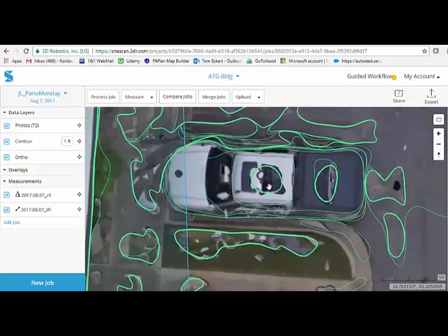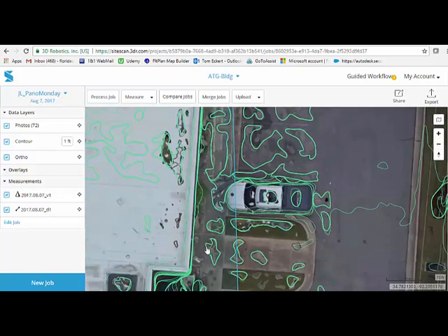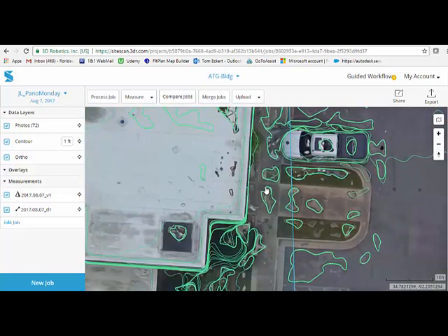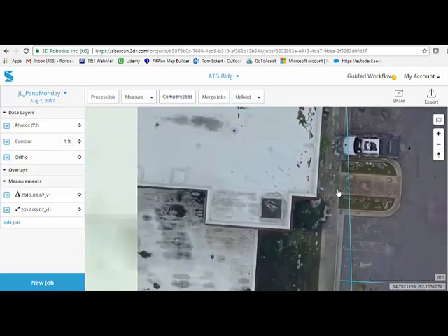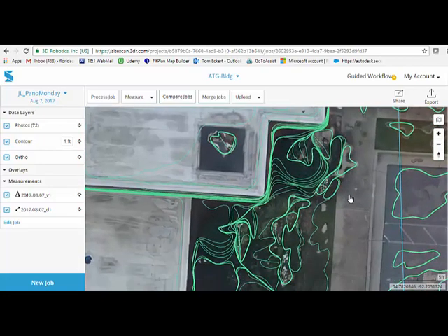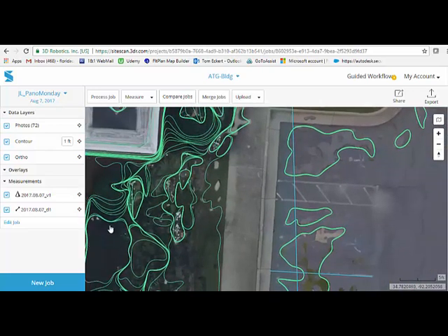So don't be fooled when you contour a vehicle as a surface object or use these contours for development without fully understanding the metadata, the point groups, and the precisions and accuracies from a full geomatics perspective. So yes, it's a feature, and we don't want you to forget that. Yeah, you can throw a contour map out, but what it is, what it looks like, and what it means are three entirely different things.